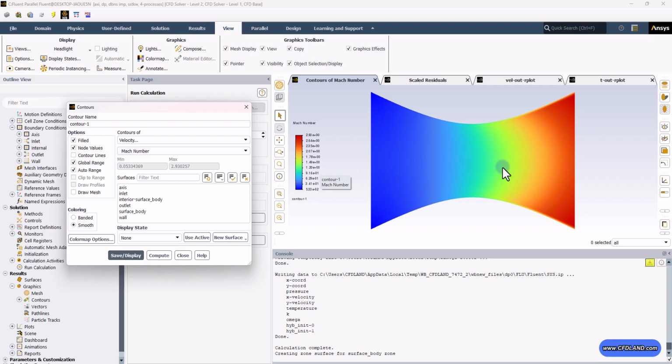So finally, in the diverging part on the right side, because the flow is supersonic, expanding the area causes the velocity to increase further, unlike subsonic flow where expanding slows it down. And at its maximum, it experiences about 600 meters per second. Since the speed of sound is roughly 340 meters per second, depending on the temperature, we have reached approximately Mach number of 1.7 or 1.8. And this all represents that this is going to be a supersonic flow in the nozzle.